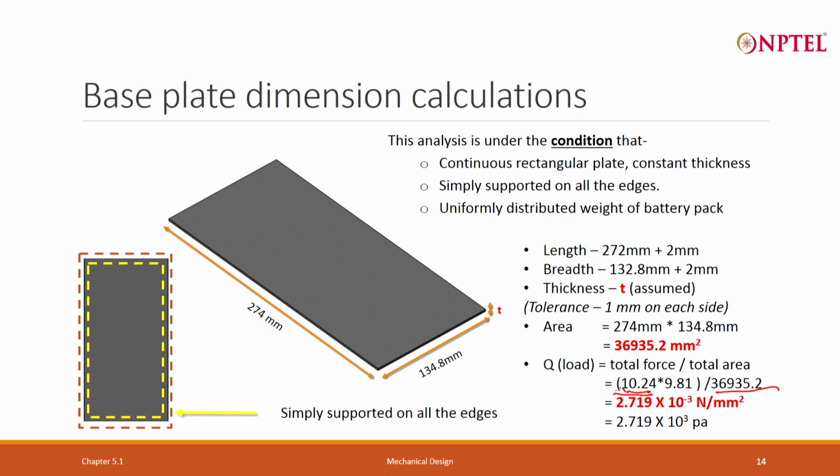With some extra tolerance of 1 mm in the base plate, we found that the length of the base plate is 274 mm, the breadth or width of the base plate is approximately 135 mm, but the thickness is not known.